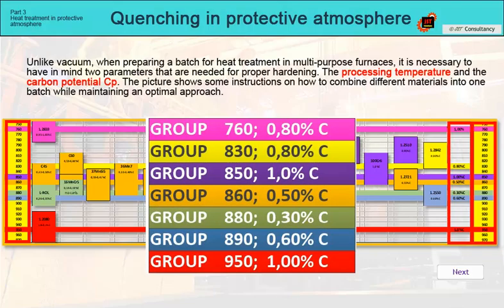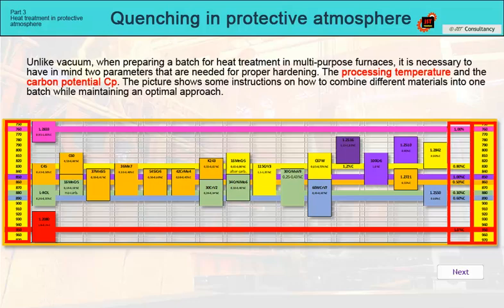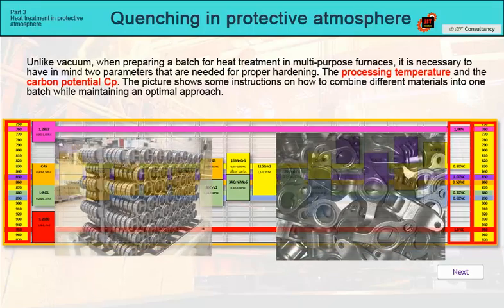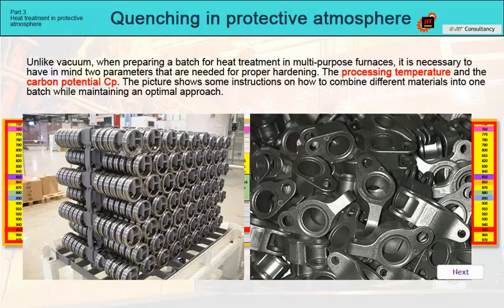It is up to the heat treater how it organizes these processes, but it is always necessary to remember that all parts should always proceed according to the usual procedures. In other words, it should not deviate from the relevant standards. Another criterion is the size and shape of the parts. In addition to the temperature and CP, it must also be met that their heating has approximately the same behavior and that all parts in the batch are completely austenitized within the set time.